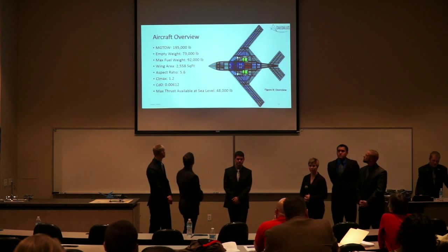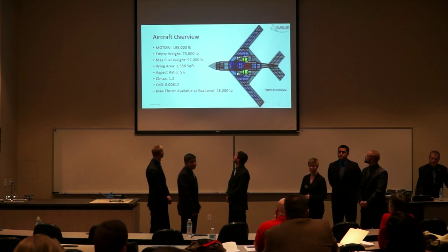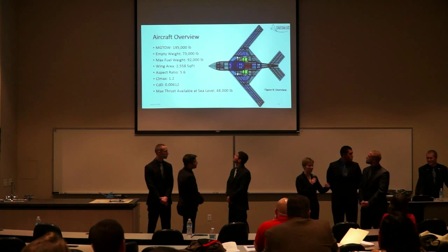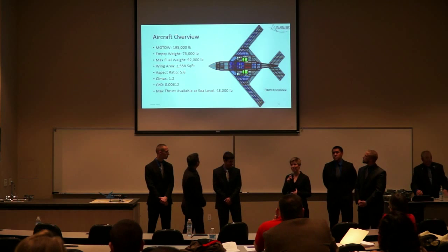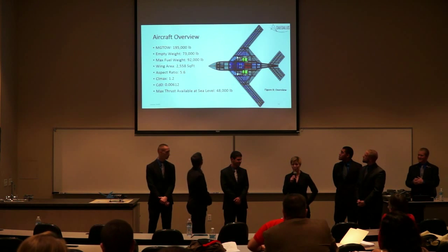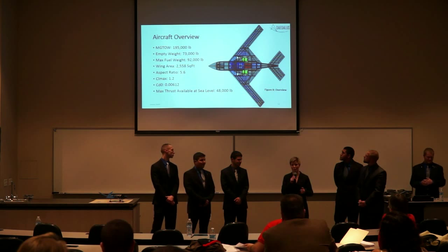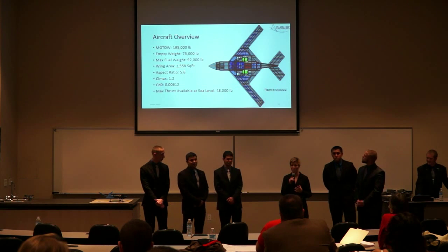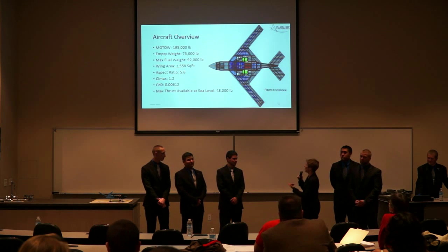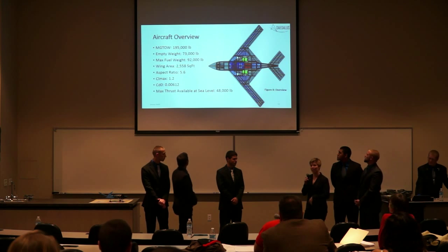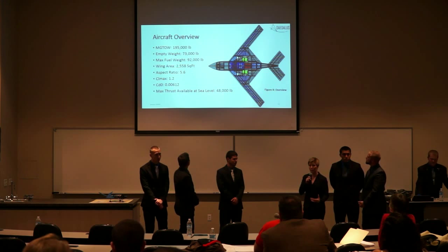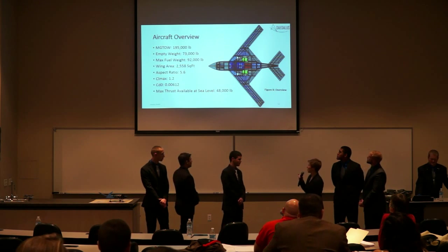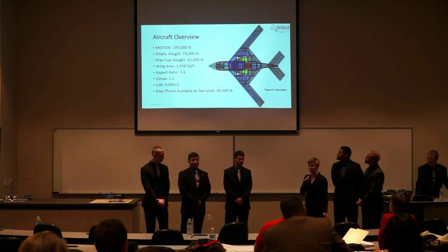So I added up your numbers. The 73 and the 92, you get 165,000 pounds. Based on some feedback that we got, we were told not to put the weights down to the pound. We were told just to conserve the significant digits and give the overall large numbers. So for our total gross takeoff weight, it's actually 195,307 pounds, and the max fuel weight is 92,220 pounds.